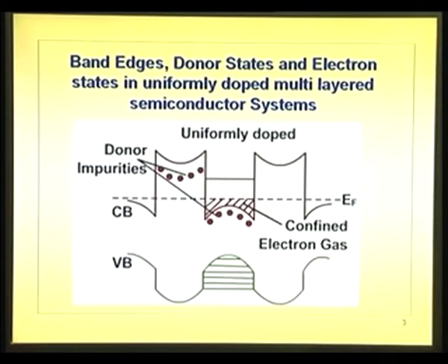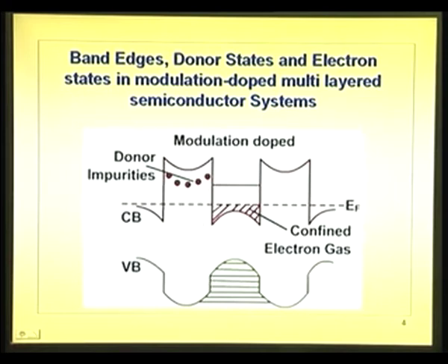But I just show one more diagram. So, this is N N uniformly doped. Doping here is the same as here. Still there will be transfer of electrons from here to here. Now, you have another situation that is called modulation doped. The transistor that is made out of this is called MODFET, modulation doped field effect transistor. It will come later, that is also called high electron mobility transistor.